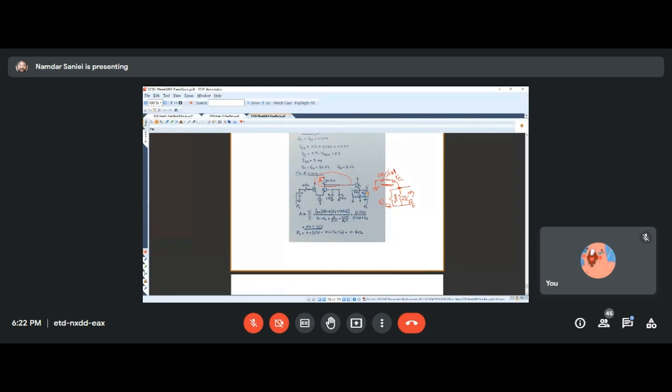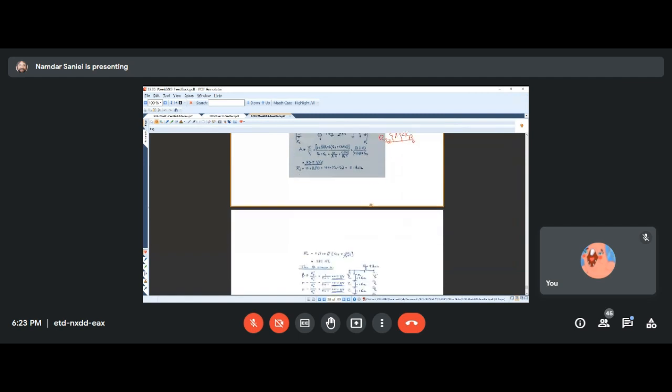The output resistance was a little more tricky. But when we looked at this node, what we saw up there was the reflected version of this to the emitter next to the little RE, going to the ground. So from this node, the series of those two were going to ground, as well as the 2K and the R22. So that was the output resistance.